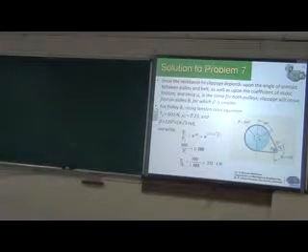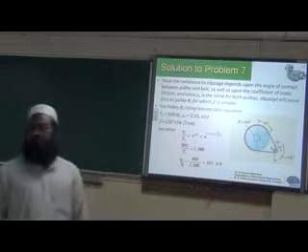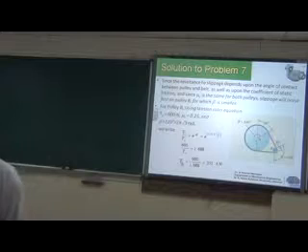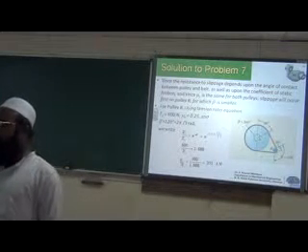Okay. We got the tension for the slack side. Tight side is given. Maximum tension is given as 600 Newton. So convert theta into radians. You must remember that. You should not forget.